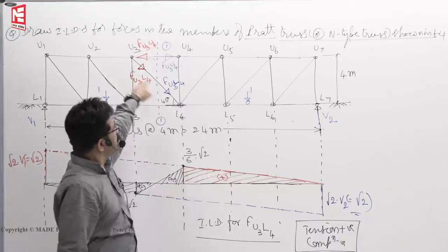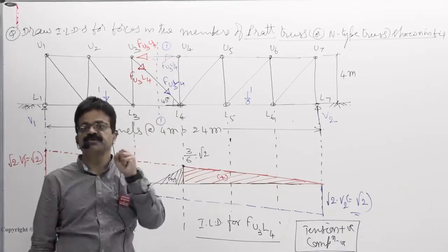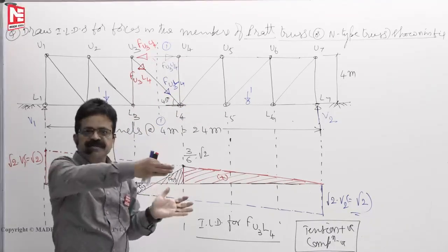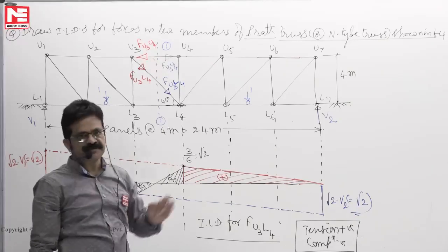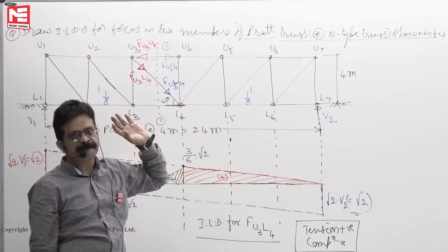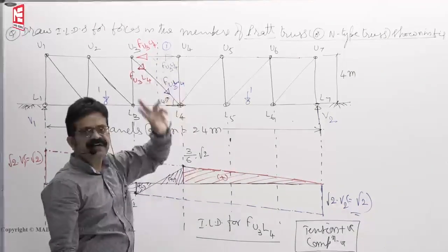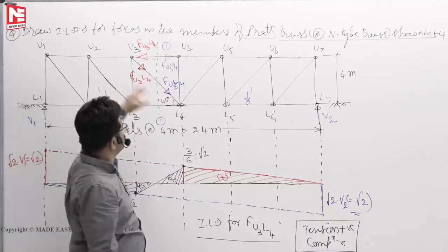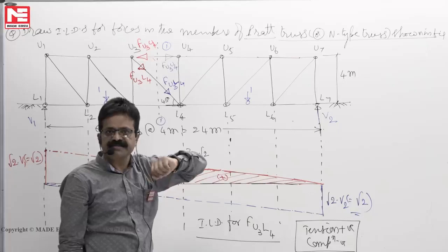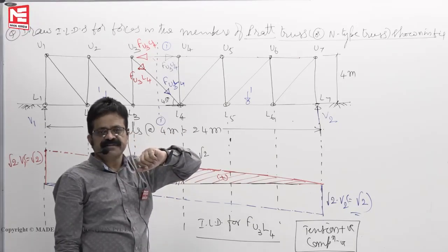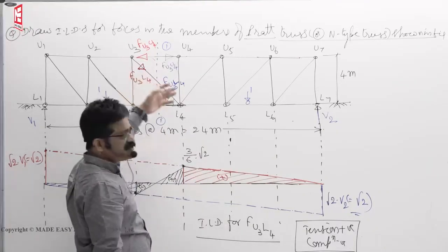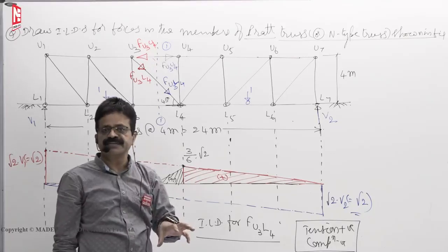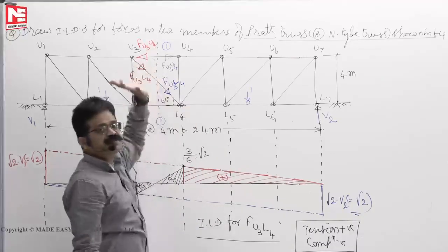So when you are designing such members, you have to take the fatigue coefficients also, and accordingly you have to size bigger, you have to increase slightly. Because if you are designing it for 100 years span, in 100 years the stress reversal can be 1 million times, maybe 10 million times. So in such cases 10 million times means accordingly fatigue coefficients you have to take and design the member accordingly.